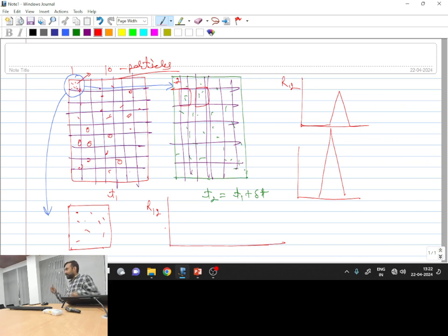So that's why you have to do many iterations also. You have to change pulses. You have to select the value of delta t. Okay, different values of delta t. You have to decide for what velocity, what should be your value of delta t. So all these things you have to do. Measurements are not very easy, like you switch on the button and then you have got the output. You have to do some trials, and then you have to identify which velocity is actually your physical one.